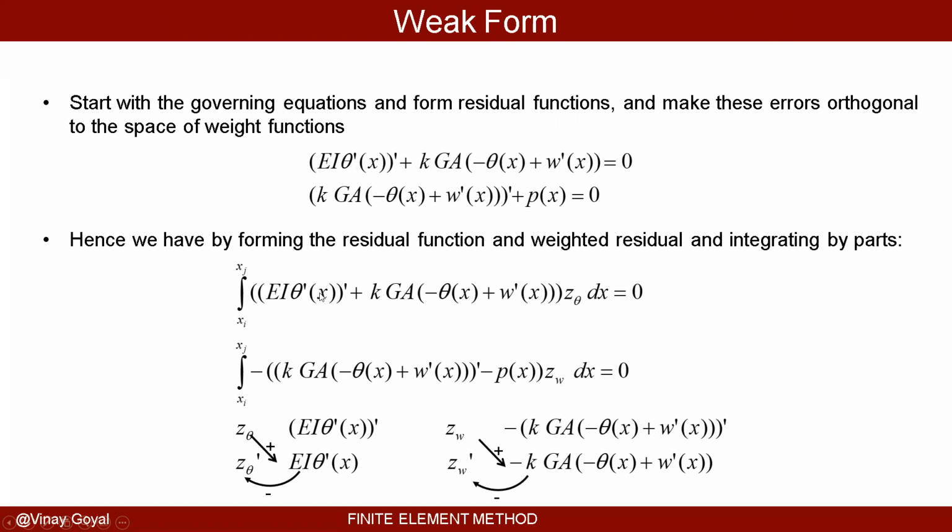This term right here can be integrated by parts. You can see I put EI theta prime prime on the right hand side and z theta on the left side. And then plus minus transfer the prime over. So now I have a single prime here, a single prime here. And what I've done is I weaken the continuity requirements by integrating by parts. That's what we have done here.